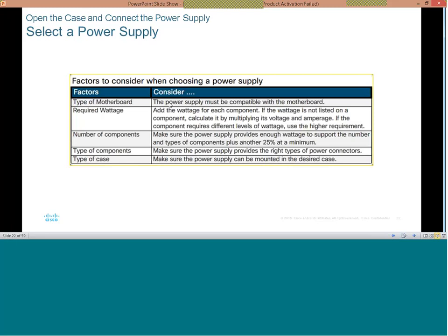You don't just pick any power pack or power adapter from anywhere just because you can plug it into your laptop. That is not the case. What we're saying is that the power adapter or power supply pack must be the right requirement for the system. For instance, a system that is supposed to take 19 DC volts and 2 ampere current, you can imagine you now using 18 DC volts with probably less than 2 amperes.